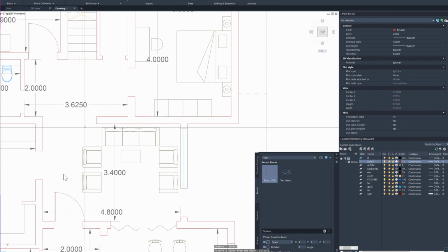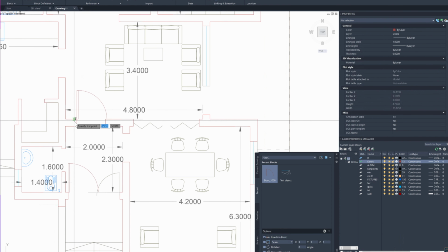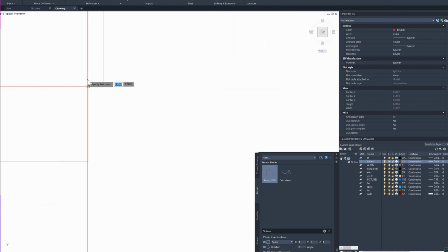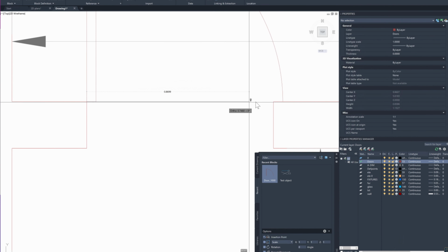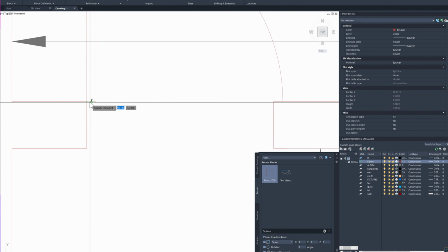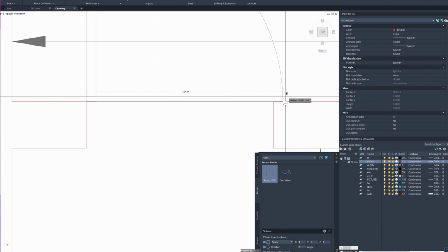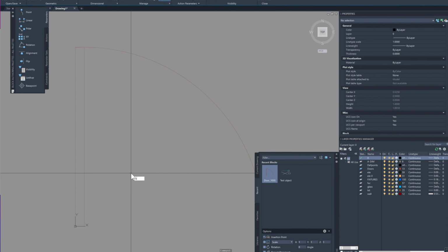Make sure that you draw the door in the correct measurement. Let's check that together and edit it so that it applies to all the versions that we have added. So let's measure the distance from here to here. That is 1 unit, and the distance from here to here is slightly bigger, so that's 1.015. So I'm going to double click on the block, select OK, and then offset this to 1.